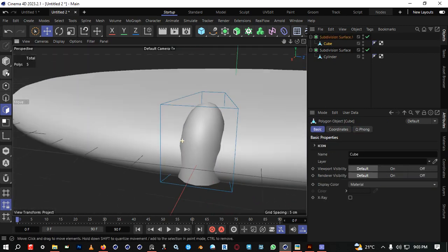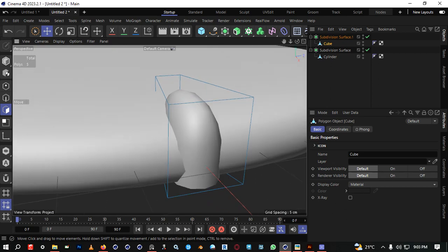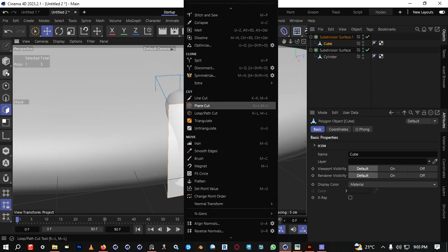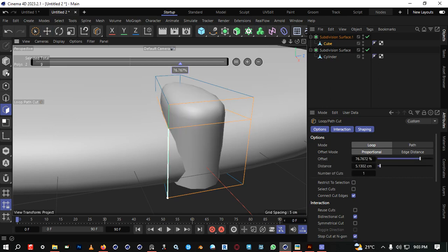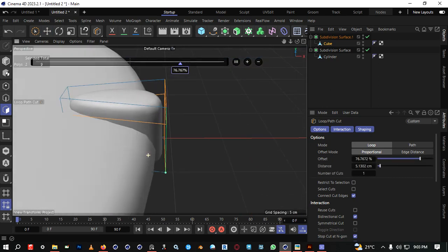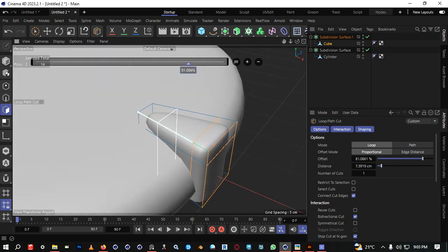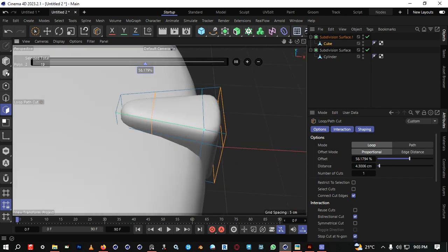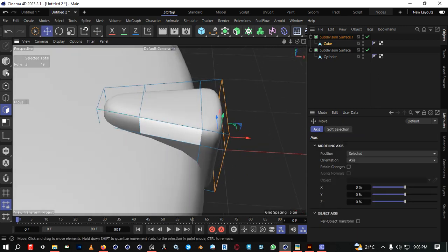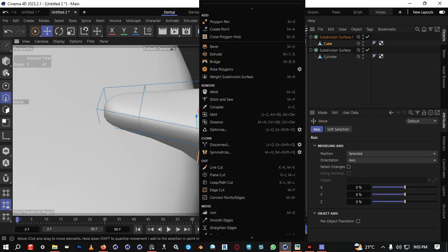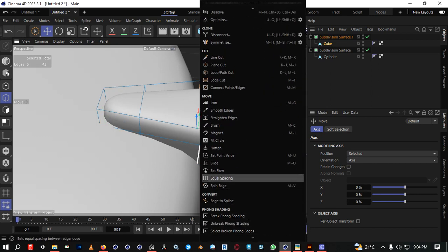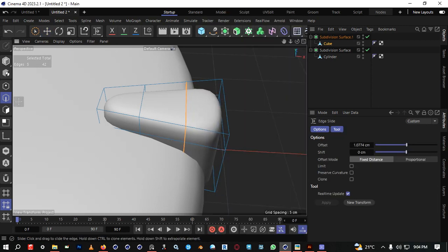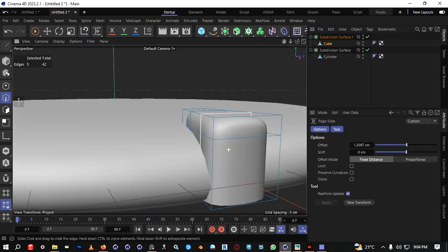Yeah, so already we had something like that. Okay, so just added in some loop cuts. Let me bring in some loop cuts, so we can add the loop cut around there, just to give it that little bit of tightening. Then we added a bit of another loop cut over there, and we can add in another one somewhere there. Then we can shift this loop cut. I think we can slide it actually. Let's go to slide edges. Okay, sorry. Then slide it somewhere here. Yeah, so we can slide it like so that we can have that kind of thing.